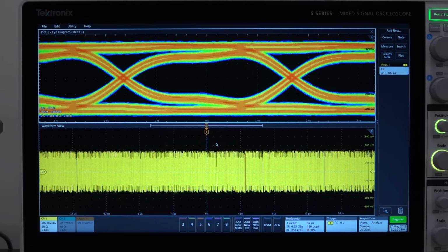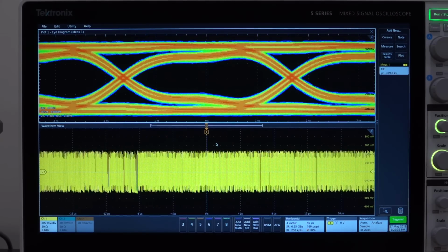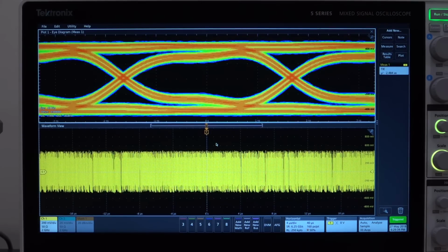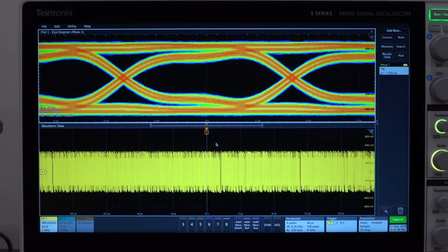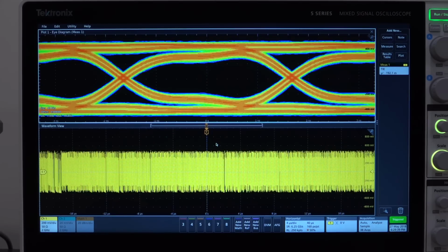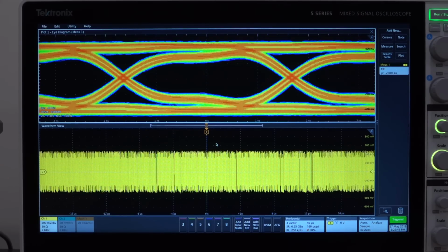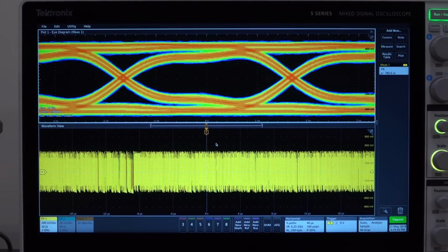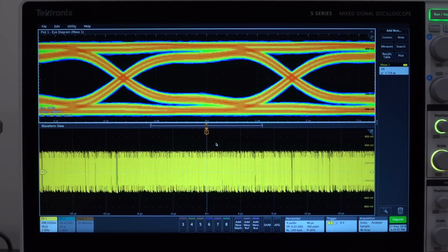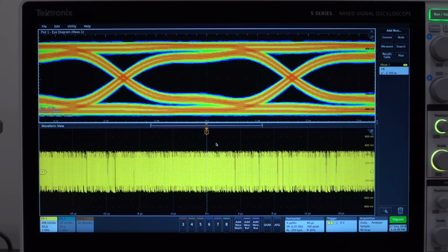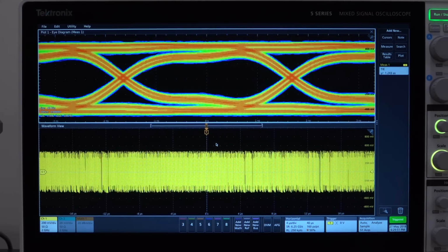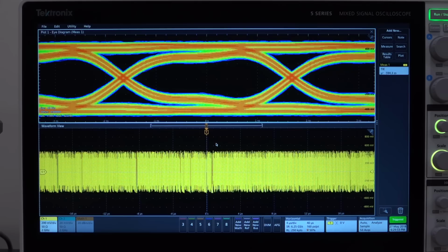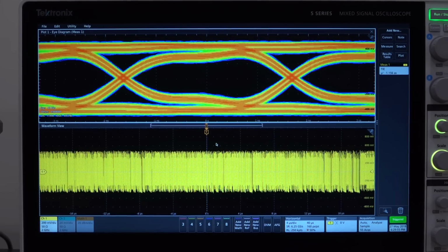And this is just 90 inch of trace. Now imagine trying to send 50 or 60 gigabit per second through a trace that is this long. It would be exceptionally difficult. And of course, a lot of research has gone into equalization techniques for that. But you can clearly see the influence, and being able to do 300 megabit per second is of course quite nice. Now I can increase the rise time from 1 nanosecond to 2 nanosecond on this eye diagram as well,